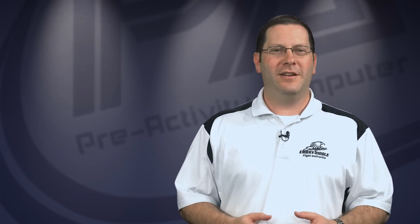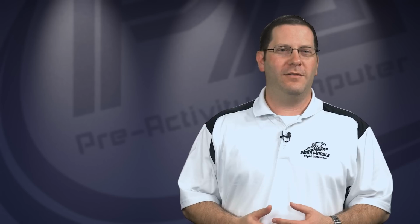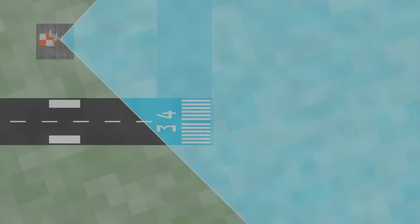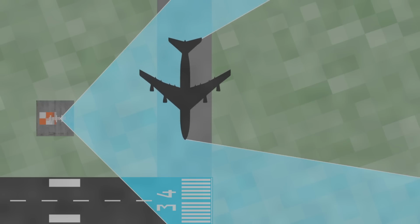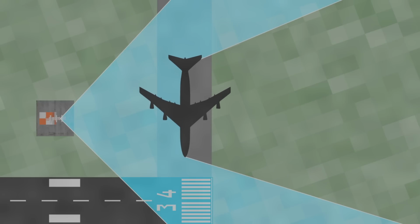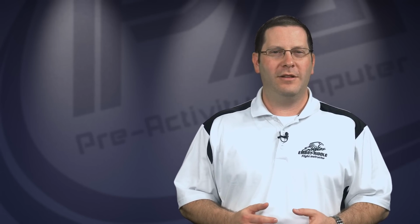Due to the positioning of the glide slope antenna close to the approach end of the runway, the glide slope is subject to another issue known as distortion. The antenna location is a place where moving objects such as other planes, airport vehicles, or even animals can get in between the aircraft and the transmitter, causing the glide slope signal to be blocked and causing a sharp, drastic fluctuation on the CDI. If an erratic glide slope is encountered, the approach should be abandoned, as the signals being received are no longer reliable.